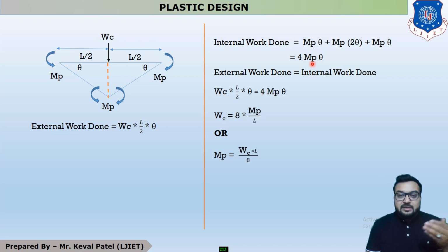If in the exam it is clearly mentioned to find out the collapse load, you have to make WC your subject, and if the question clearly mentions to find out the plastic moment, you have to make MP your subject.